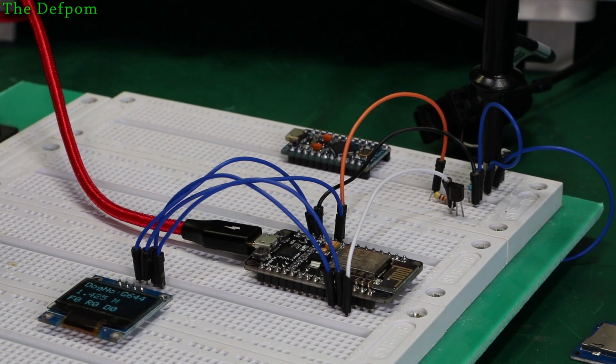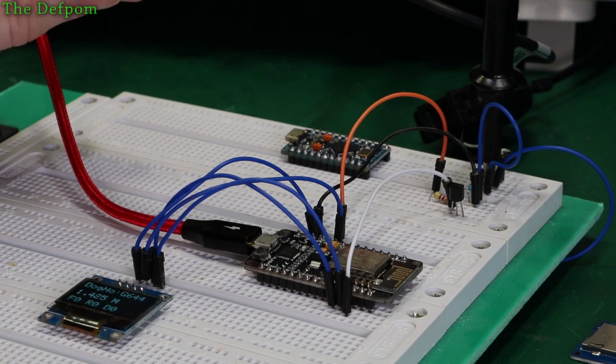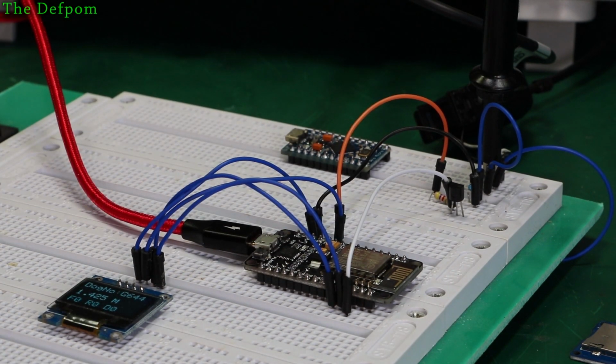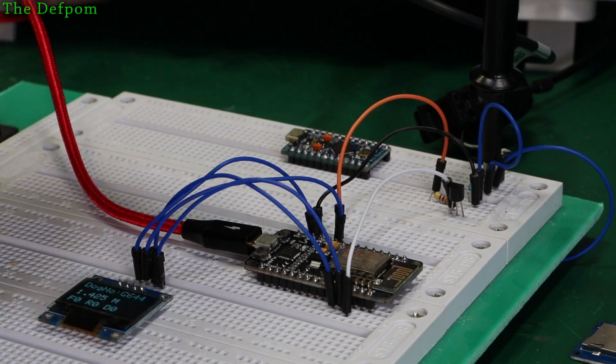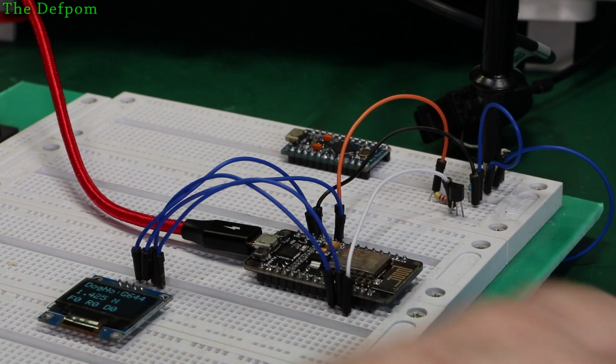You can buy level converter transistors or ICs or whatever. You can buy those devices quite easily, they're pretty cheap. Level shifters, which actually go bi-directional as well. But in this case, I didn't require that, and it's just easy parts, a couple of cents worth of parts, not really worth worrying about. So that works fine. Now I'm going to scope probe it. Well, I've already got a probe in there, but I'll scope it and I'll show you what signals we're getting and what I've discovered so far.